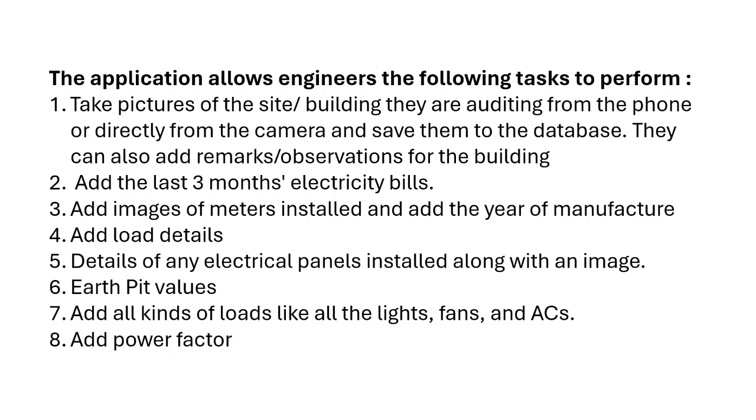They can add load details on the energy meter. They can enter the details of any electrical panels installed previously along with an image with a remark, also earth pit values, and all kinds of loads like all the lights, fans, ACs, etc. And they can mention the power factor also. And yes, the company is using it for its energy audits. No problem so far. Everything's working fine.